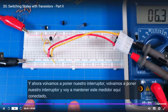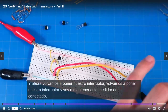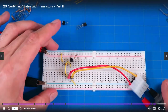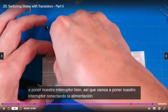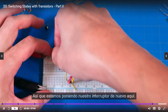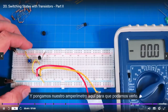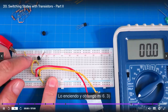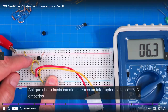And now let's put our switch back. I'm going to keep this meter hooked up over here, but I'm going to put our switch connecting the power, so I can show you this. Let's put our ammeter here so we can see it. Now there's no current because it's off. There's no base current, so there's no collector current. Now I turn it on and I get my 6.3. So now we basically have a digital switch with 6.3 milliamps.